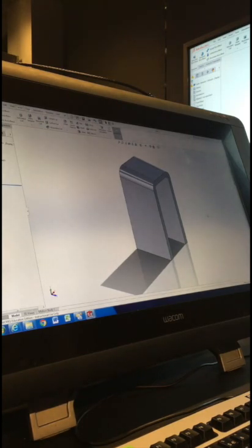And yeah, that's it. Okay, so it's because the radius is 5, but your offset is also 5. If you change that offset to 3, that will change those. The other thing is that bottom line should be for construction.